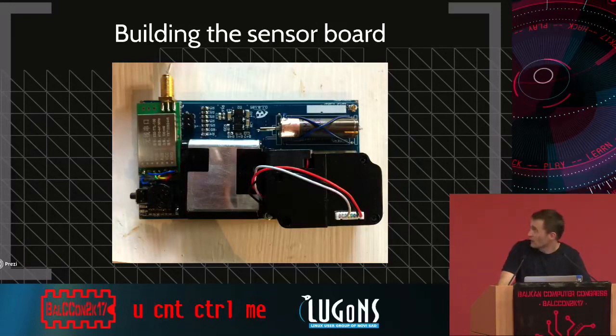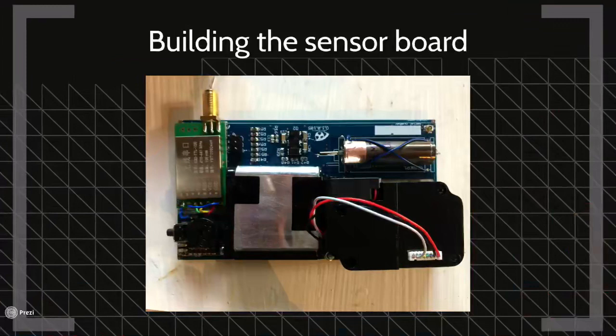a 500 volts multiplier on this thing. You can see the black SMD blocks at the center top. Those are actually high voltage diodes. Those are part of the multiplier circuit providing the high voltage.